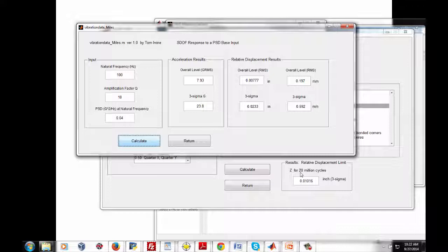Now, having said that, there are reasons why sometimes we cannot mount the outside housing via isolator springs. Maybe the box needs to be hard mounted. Maybe it's a transponder that puts out a lot of heat energy and it needs to be hard mounted to a thermal ground plane, and some intermediate solutions like a thermal grounding strap would not be good enough, so it has to be hard mounted. We cannot use isolators. So in that case, with some caution, I would still encourage a stiffer board with a higher natural frequency to reduce the relative displacement. But things are not always so simple.